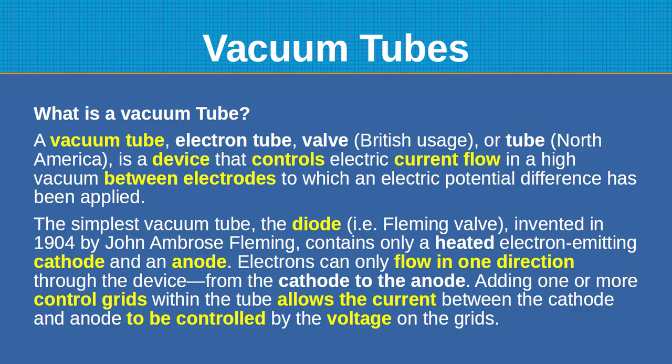And the other element, because it's a diode, we call an anode. We change it to a plate when we make it a triode or tetrode. It would attract those electrons with a high enough voltage, and you would have electrons flowing from the cathode to the anode, just like in a diode, where we would say conventional current was flowing from the anode to the cathode, but it's really those energized electrons that were ejected from the cathode that are being attracted to the anode.